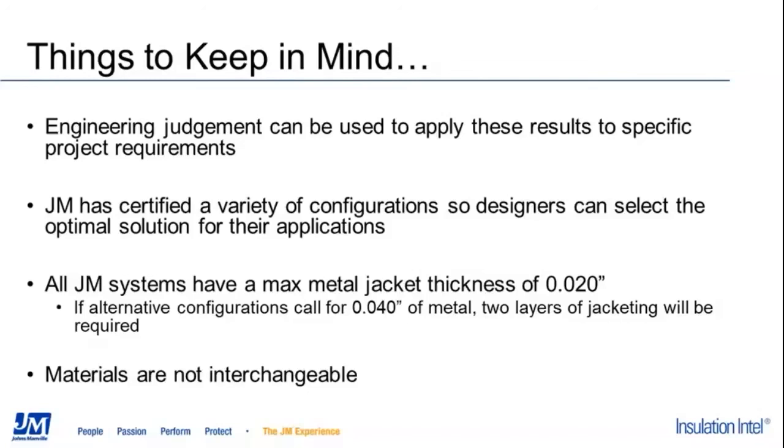And as Jake pointed out earlier, it's very important to remember that materials are not interchangeable. So you can't substitute a different mineral wool material for the material that we have certified in here, and assume that it's going to meet the requirements.